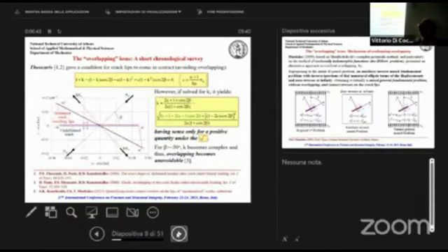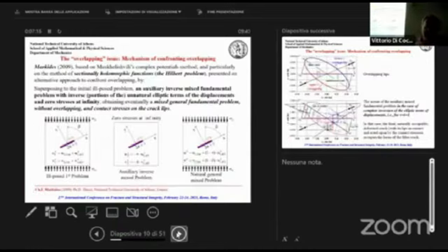So Harry's team, my mentor's team, also made work in this field, and they gave a condition according to which overlapping could be avoided. Unfortunately, if we look deeper in the solution, it seems that under specific combinations of load, geometry, and material, overlapping cannot be avoided. And for their solution, after 50 degrees of crack inclination, overlapping is again a result of the theoretical analysis.